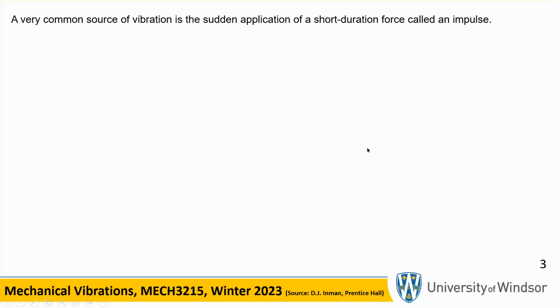Okay, so a very common source of vibration is sudden application of a short duration force. That's exactly what I was talking about. A very short duration force applied on a block. And that kind of function is called an impulse function.